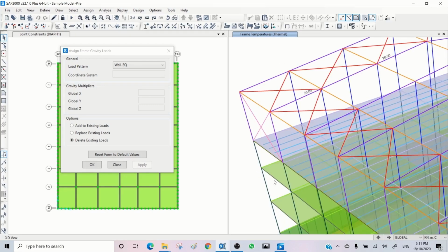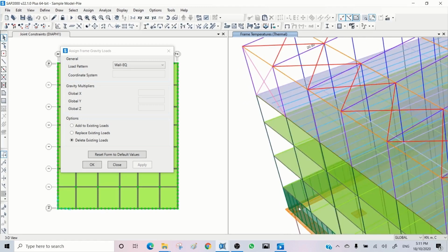What SAP does is calculate all loads above the floor up to the next floor plus this floor and lump it to the mass. So when you have all typical walls coming, they are almost similar if you have the same wall material. So you have the full height of the wall for each floor above the floor. But when you reach the top floor, you don't have the mass of half of the height of the wall below. So how can we make it correct?